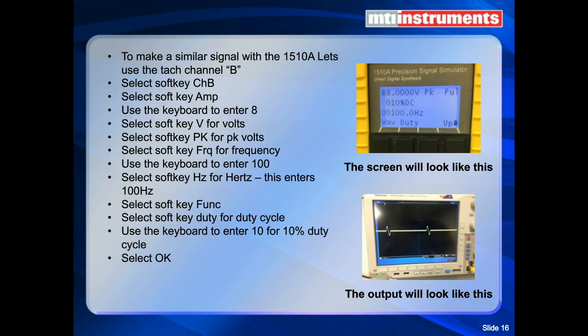On the oscilloscope display, you can see the pulse's output there. So I could either have something that looks like a continuous sinusoidal or a pulse output. Once per rev output for tracking the speed of a machine looks more like what you see in the oscilloscope there. So what we could then do is input this into our system to see what we read, if we're correctly reading the speed, if your time base and your data acquisition system is correct.